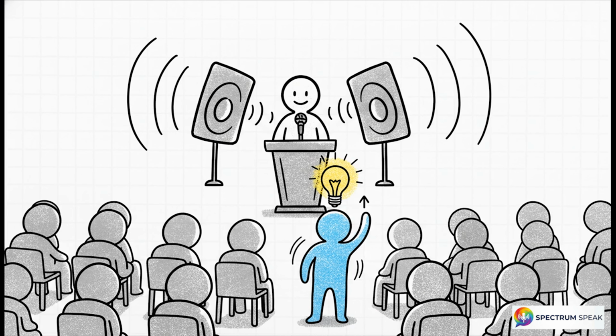And that brings us to our never-forget visual analogy for this explainer: the town hall meeting. Imagine a crowded town hall. When someone has an announcement, they step up to a microphone and just broadcast their message over the loudspeakers to the entire room. They don't walk around whispering in individual ears, right? Every single person in that room hears the announcement. This is exactly how CAN works. It uses broadcast transmission. When a node sends a frame of data, every other node on the bus receives it.